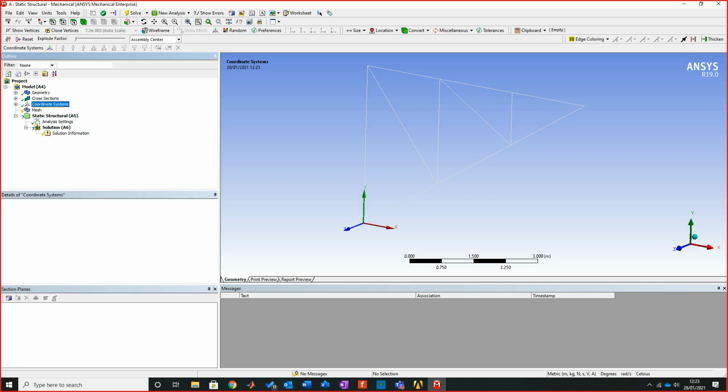Then, coordinates-based measurement. The coordinates allow us to give it a point of origin for beginning. But we can move this coordinate, we can make this coordinate move in particular ways. We can simulate a linear actuation motion. So if we know the displacement of that linear actuator, depending on the component, we can tell it which way it will move to look at the force as a resultant. But with this, because it's fixed to the wall and because it's a result of us applying 10 kilonewtons to it, it allows us to really look at the overall picture.